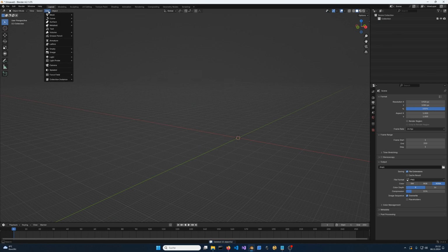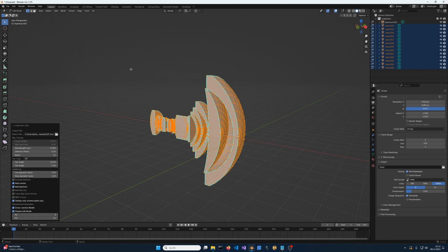So just delete everything. And now in OptiCore Optics, we have this option to reset performance critical settings. If I just click this, it is basically instantaneous. And now go back to loading the lens from the zmx file. Then the number of vertices of the mesh, as well as the number of rays in our ray fan, have been reset so that we're back to a good performing solution. All the other settings are unchanged, as you can see, for example, from the file name still being selected as before.